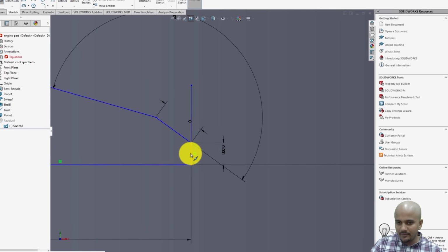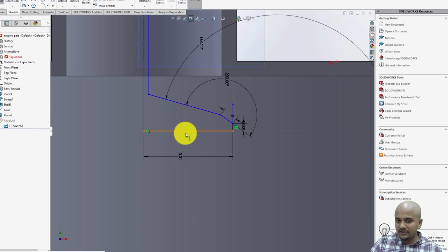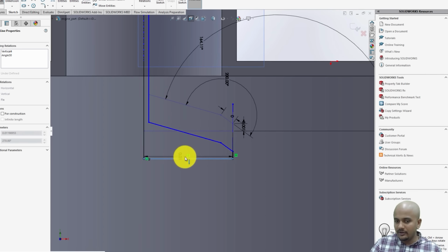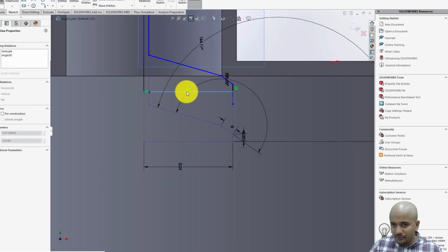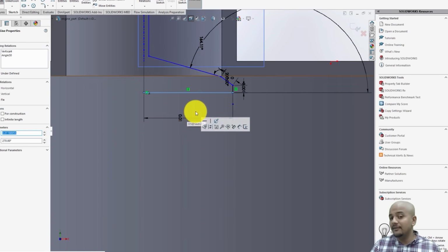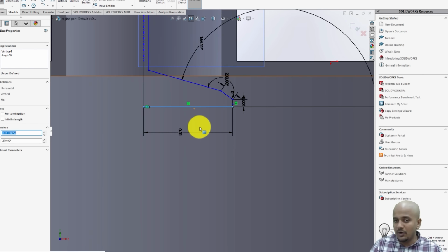So in this case, for example, I am setting the size of the critical valve dimensions and angles. When I do that, what I can do is I can just drag a particular line in the valve, and I can actually vary the valve lift. For those of you who don't know what valve lift is, it is basically the distance by which your valve is actually pushed open. So in other words, if you basically do something like this, this is where your valve is just about closed, so the valve lift would be 0. And if I just open it like this, that's valve lift of 1 mm.